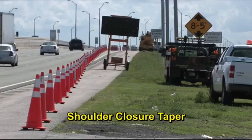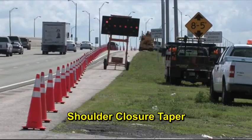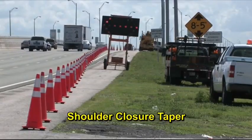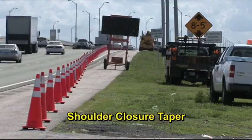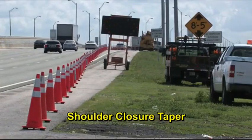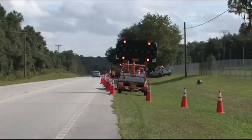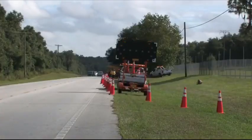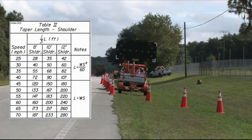A shoulder taper may be beneficial on a high-speed roadway where shoulders are part of the activity area and are closed, or when improved shoulders might be mistaken as a driving lane. When paved shoulders having a width of 8 feet or more are closed, use channelizing devices to close the shoulder in advance of the merging taper to direct vehicular traffic to remain within the travel way. Shoulder taper formulas can be found in the Design Standards Index 600 series.